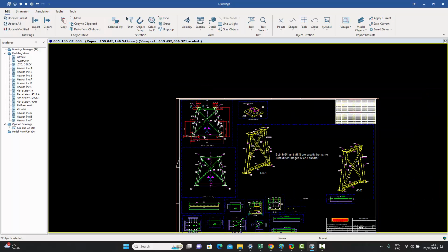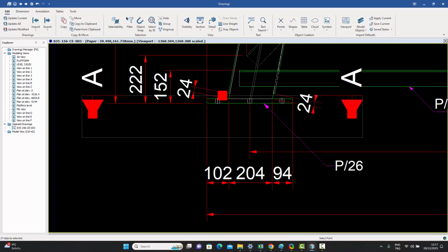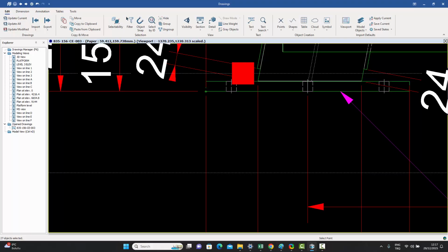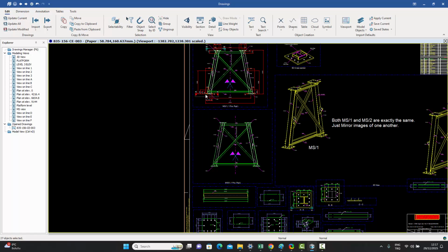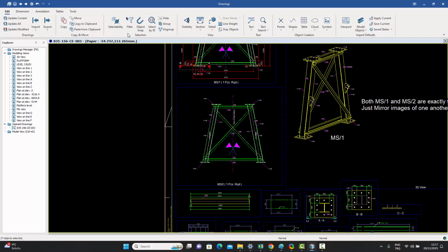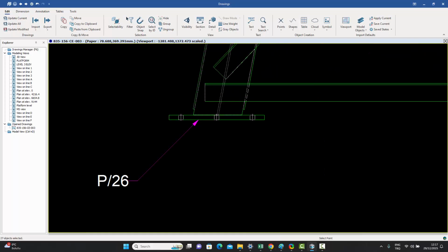So you've got the dimension selected and the section AA selected. Now if I go over here at the top, it says copy to clipboard, and when I click on that, it asks for a reference point. I'm going to show the bottom left corner of the base plate. Now, since a very similar situation exists in this target viewport, I can just say paste from clipboard and show the same reference point over here.